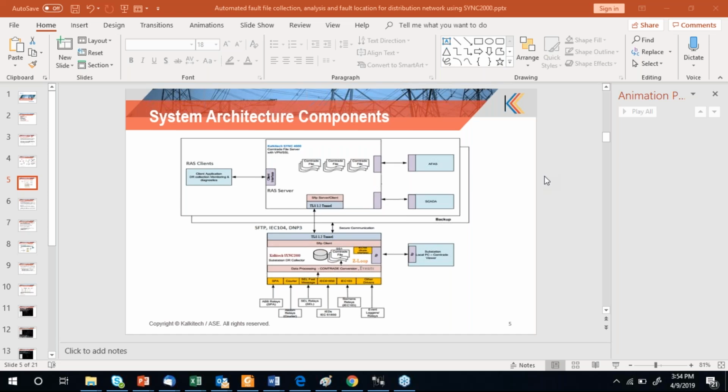So the analysis system will have the COMTRADE file, plus the events extracted from the COMTRADE file, plus live events from the IEDs also. So the answer is yes, we extract the events from the COMTRADE file and make them available in the event list, and we are working on making them available in CSV format from the COMTRADE as well.